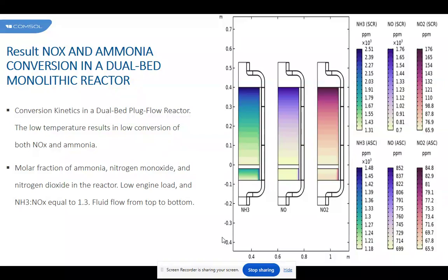Thin wall monoliths generally have a lower bulk density and hence a lower thermal mass. Moreover, a low pressure drop is advantageous because it reduces fuel consumption. Pressure drop depends on both the OFA and the channel size, with larger channels giving a lower pressure drop.